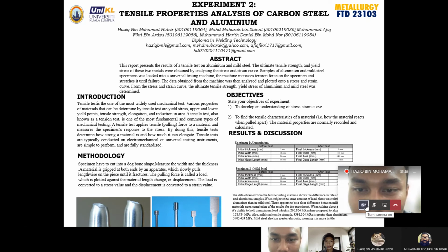By doing this, tensile test determines how strong a material is and how much it can elongate. Tensile tests are typically conducted on electromechanical or universal testing instruments, are simple to perform, and are fully standardized.